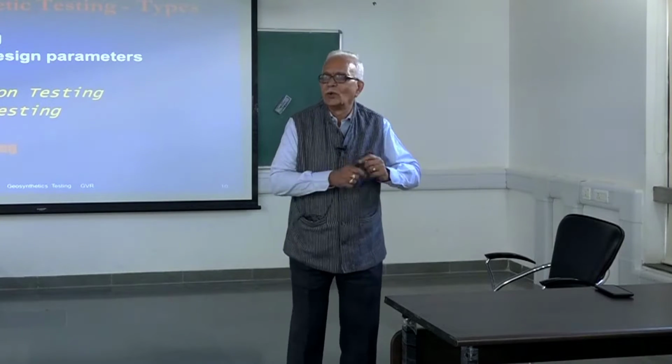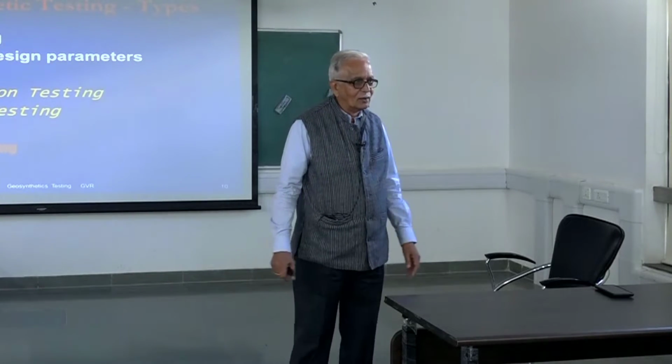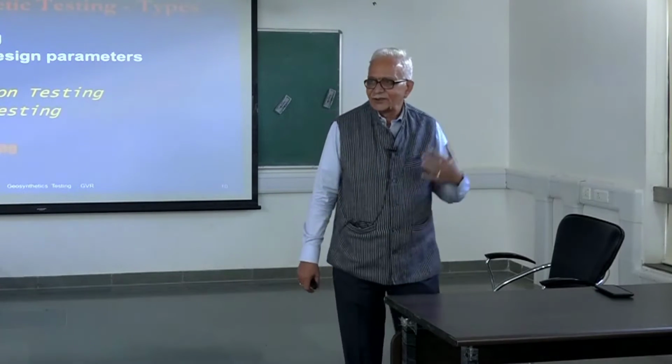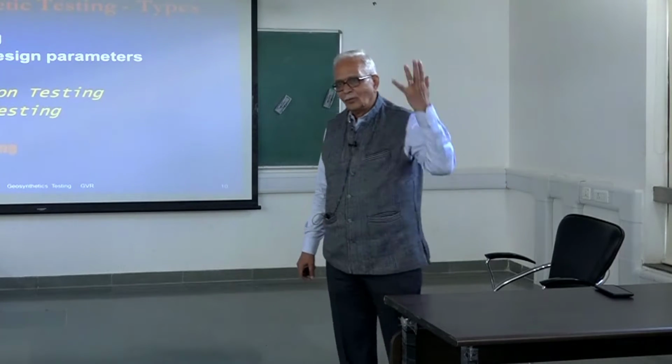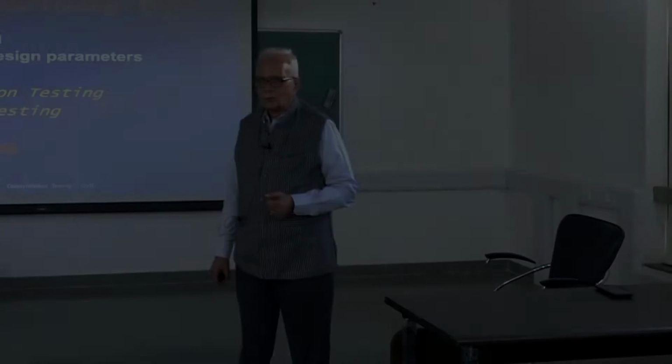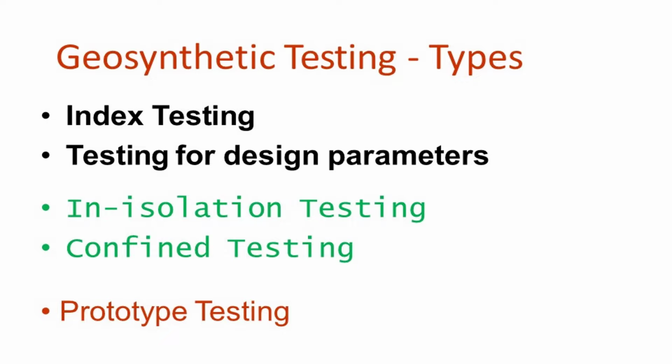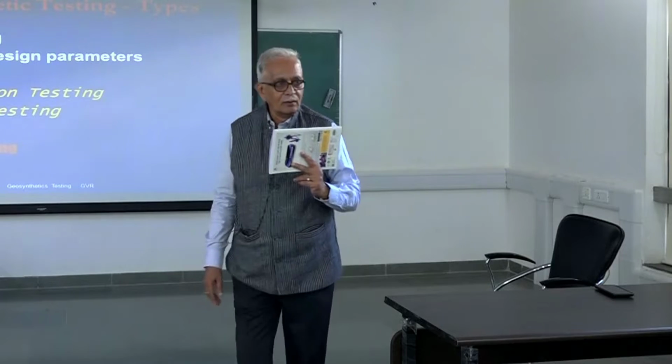It's good if I test the whole width, 5.5 meters. If the capacity of this is, let's say, 100 kilonewtons per meter, how big a machine am I going to have? So in concept it's very easy for me to think that I will have a full specimen, a very huge specimen, and you know what kind of grip I am going to have. I am going to test a sample like this, a specimen like this.